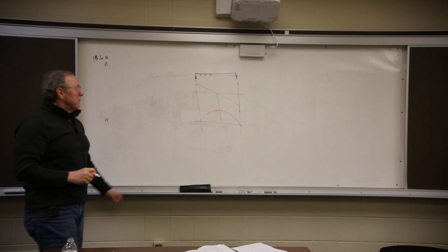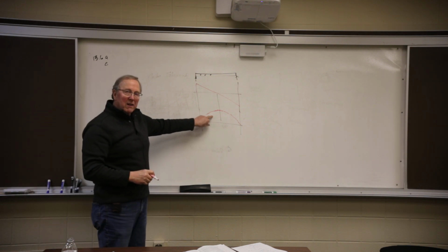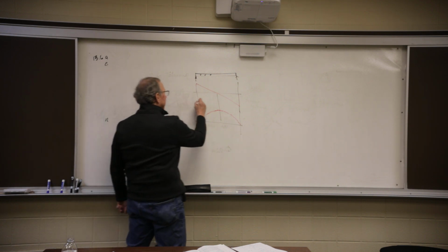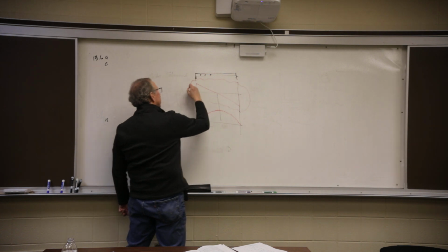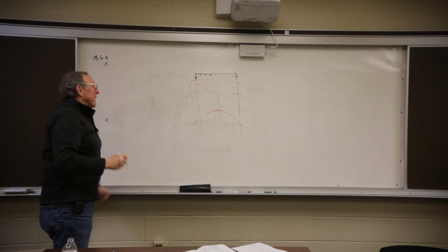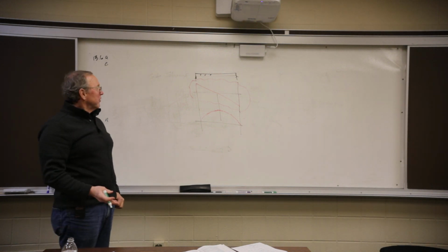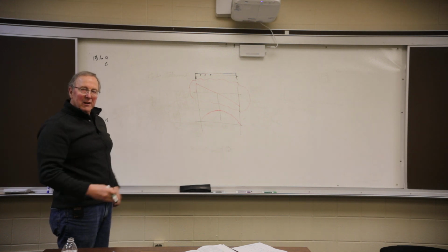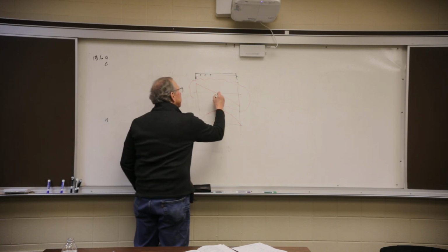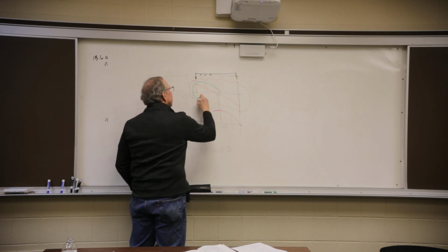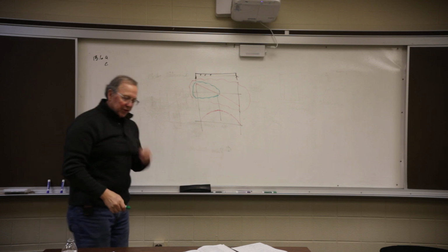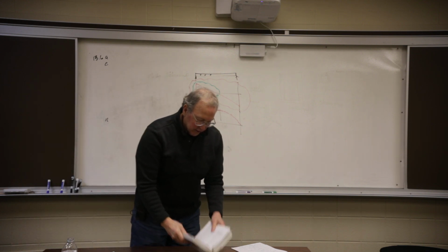We are worried about longitudinal steel, the moment governs; stirrups, shear governs. So there's my picture right here. So this picture tells me what's going on internally as far as shear is concerned. So you can see it's symmetrical. Since it's symmetrical, there's no use doing both sides. I can do one side and then mirror image it to the other side, and we're all set. So this from here to here is a drawing that we're going to produce that allows us to determine the state of stress inside the beam.